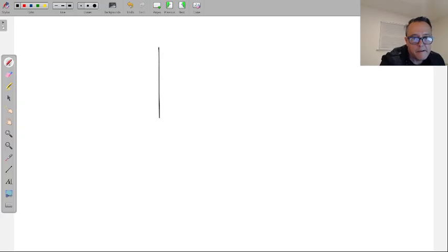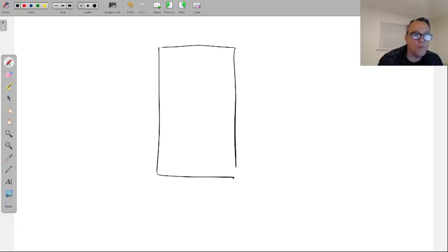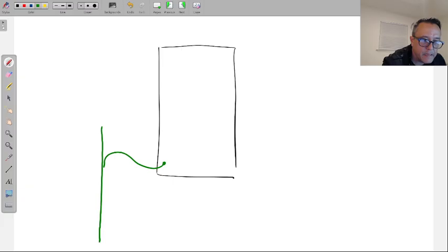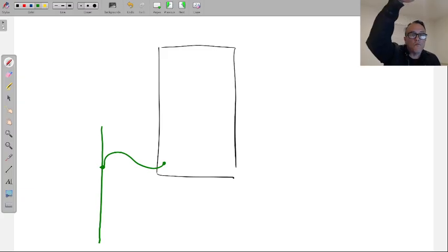All right. In a panel, we have a wire called the grounding electrode conductor. This wire goes to a ground rod, a piece of metal that gets buried, minimum of 8 feet, but the rod itself, when you buy it, is usually 10 feet. And so you drive it 8 feet into the dirt. This is in every house, building, or anything. You have to have this ground rod buried into the dirt.